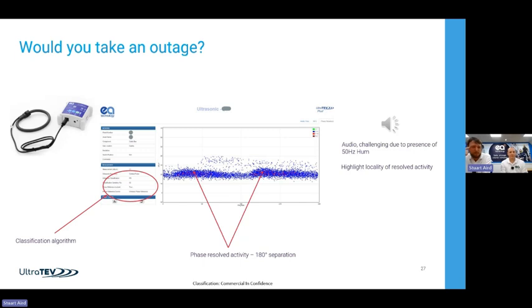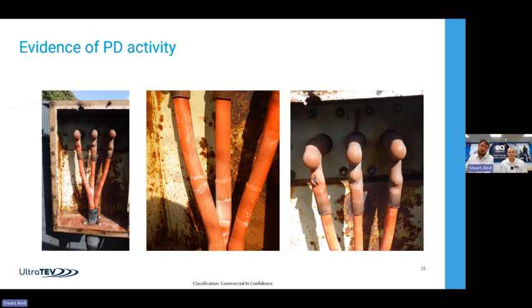Because one of the bolts has just snapped and it's all very shiny on the outside of this gear, we had the confidence to continue, and internally this is what was found. So this isn't the same transformer as in the example picture at the beginning, but you can see the metalwork to the left of that first picture. It's well painted, it's well maintained. From the outside of this, you wouldn't have had any visual indication of any issue.